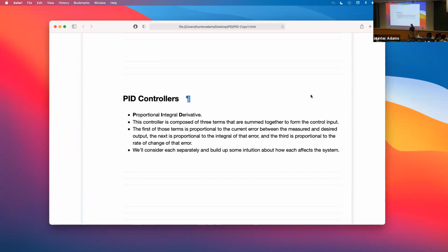Is that correct? So as we're going to talk about, the unit of angle that I recommend you use for this is ADC units. You're going to do some sort of a unit conversion because the user is going to enter the desired angle either in radians or probably degrees. I recommend that you take that user input, convert it to ADC units, and do all the control in ADC units. Yeah, so is that portion still prone to environmental changes?